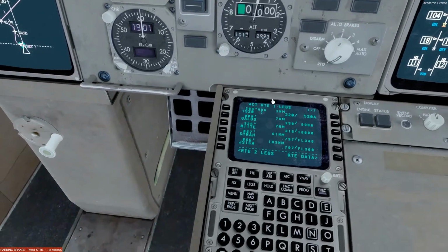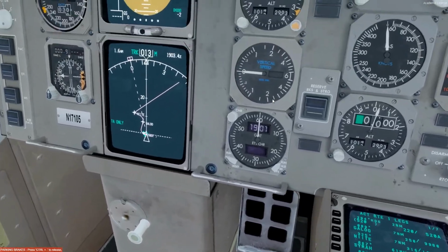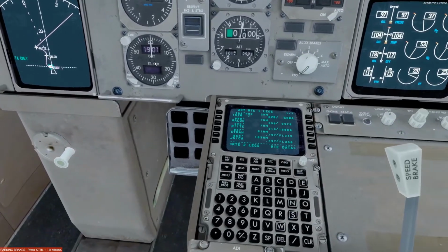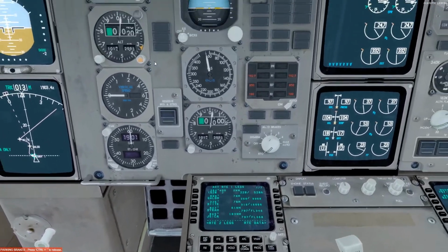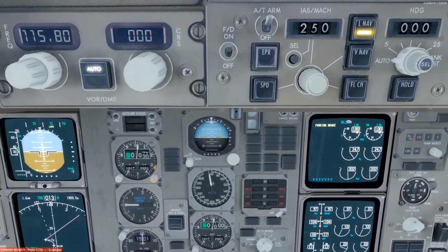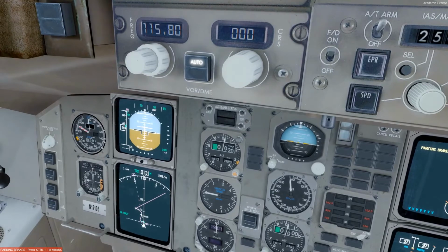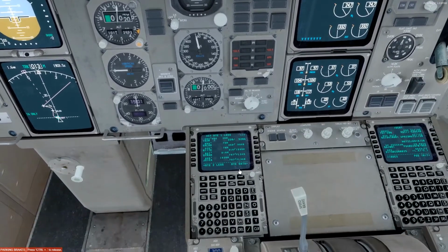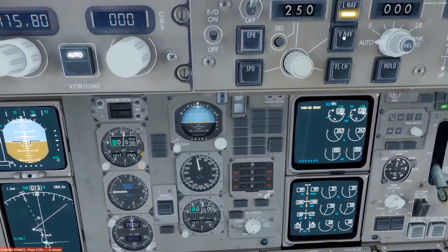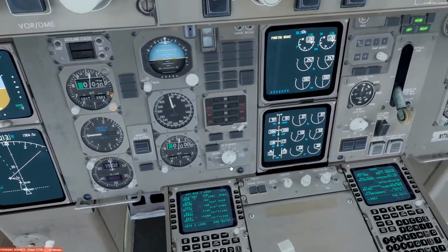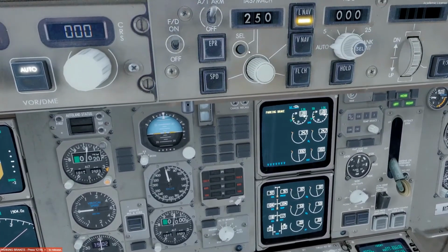And if the autopilot's not on, then all the pilot needs to do is just follow the flight director. So the LNAV will take care of the lateral component of it, which will make sure it follows this curve over here. VNAV will ensure that the plane will meet those altitude and speed targets. But we're not going to enable that just yet.